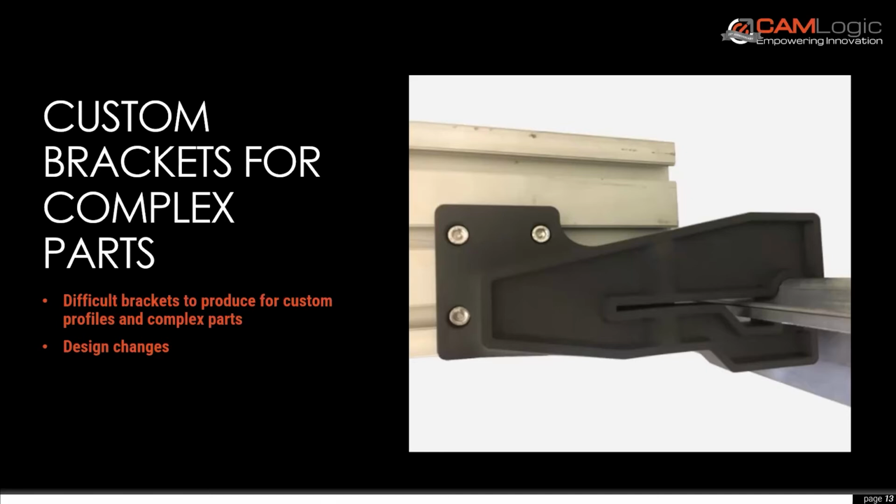They tried to machine parts and things like that, and it was very costly. It was very complex. So with some design intent going on, this part was designed. They had the CAD and everything, so they were able to do a subtraction from basically a block of material in their CAD and design this part for additive manufacturing that clips onto the part perfectly. They're able to assemble it with a non-marring material, and then they're simply able to slide this piece out of that bracket, put the new one in, and keep production going from there.